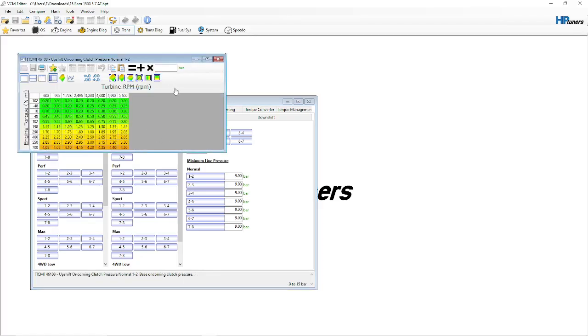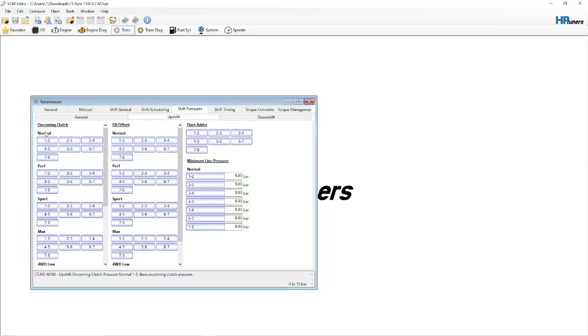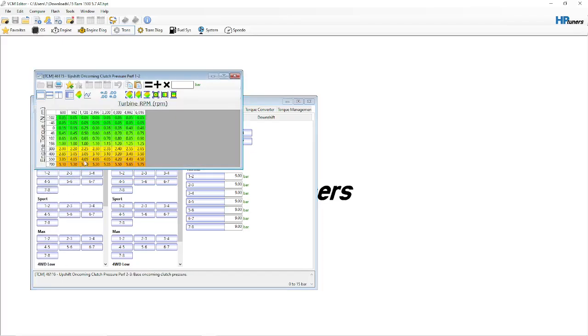This is really where it comes into another really important attribute, the oncoming and offcoming of the clutch. But as I mentioned a moment ago, this one has normal, preference, and sport, or max, or 4 high, 4 low. So again, you have to go through and adjust all these parameters. This one's reading this off in pressure. Engine, Newton meters, turbine of the transmission.